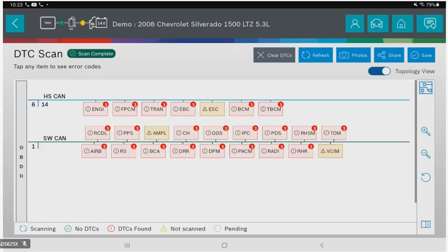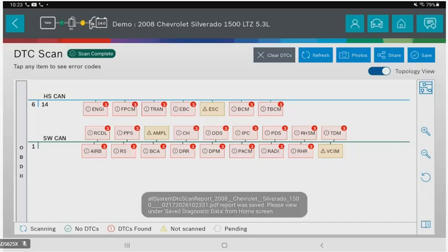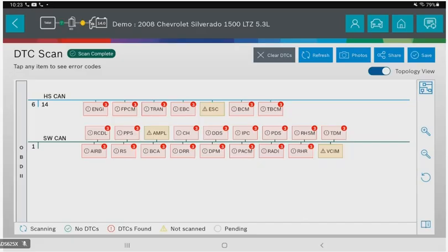It lets me look at all of them in succession, and then I can look at the trouble codes that are in each module. So hopefully when you guys are hooked up to a vehicle, you don't see this many codes in each of the modules, or that's a mess. But this is the demo program in the tool to give us something to look at, right?